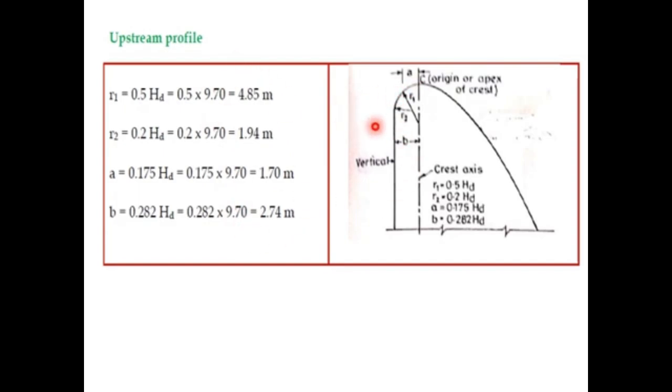So we have discussed spillways, particularly the Ogee spillways: how to use the discharge formula, which is given by C L_e H_e to the power of 3/2. We also discussed how to take the coefficient of discharge, what the various factors are that affect the coefficient of discharge, when we have to consider high spillways or low spillways, and what the corresponding values of coefficient of discharge are.